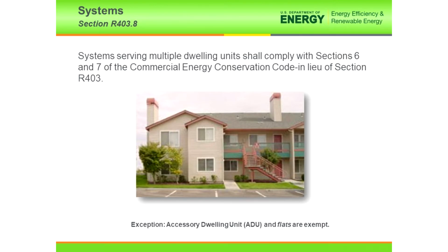So here's a for instance. You have an ADU that's in the basement, and the main structure has the first floor and the second floor. But the heating and air conditioning system for the entire structure resides in the basement. Now, the thermostat for the main structure is usually on the first floor. So now you have the person who may be renting the basement, and he has no control over the thermostat. The thermostat is controlled by the conditions of the upper floor. So now he's at the mercy of the first floor thermostat setting, which may not be the right setting for him or her.